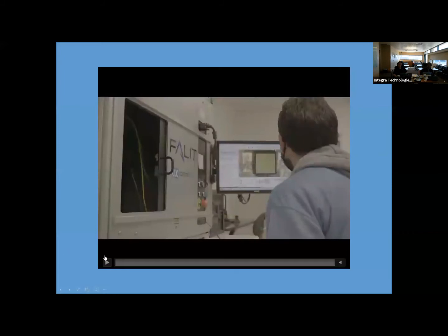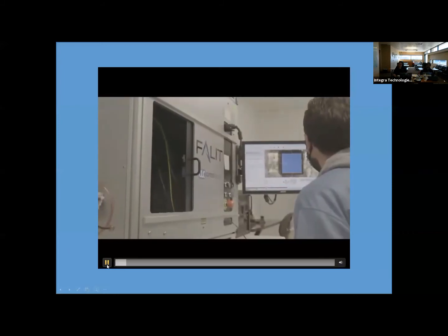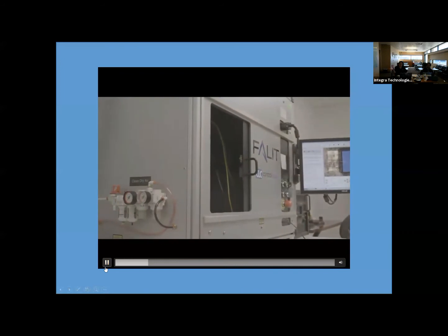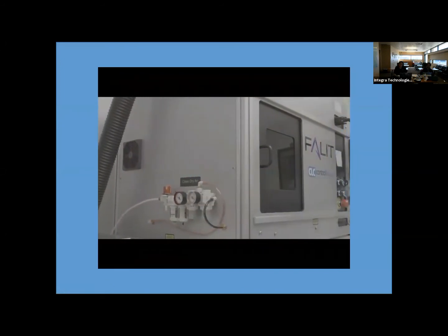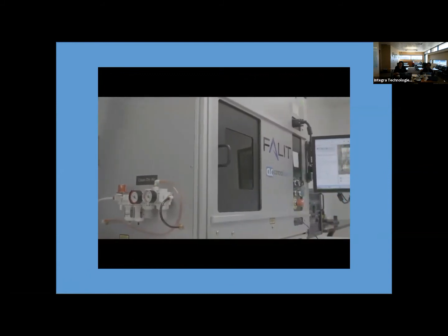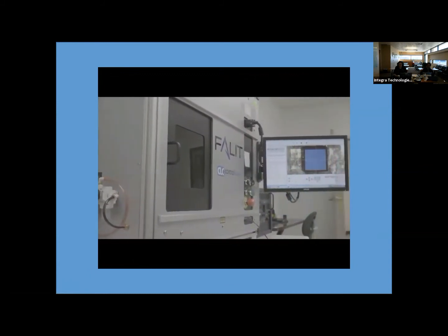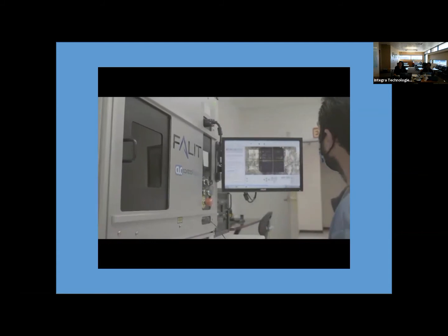What we're going to show here is a little video of laser ablation. In the chamber itself, we have the device. At this time, the technician turns on the vacuum to pick up all the additional residuals that are being ablated. On the screen there, he's showing the device of interest, and now it's showing what is being lased. At this point, he created a map of what he wants lased, the material he wants removed. He creates a cavity or a trench and prepares it for chemical processing.